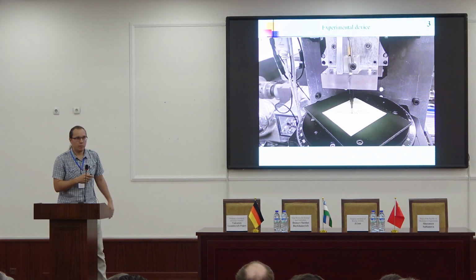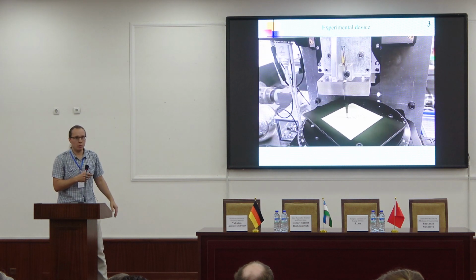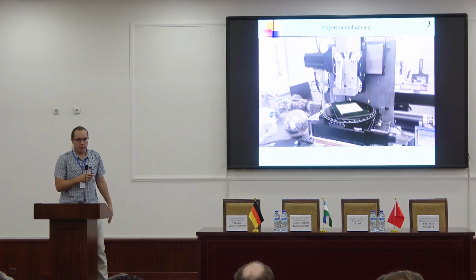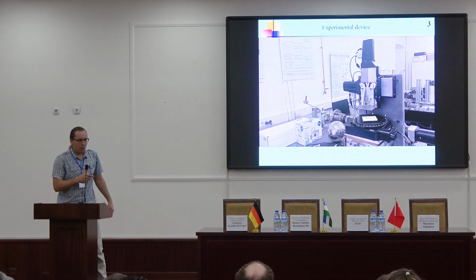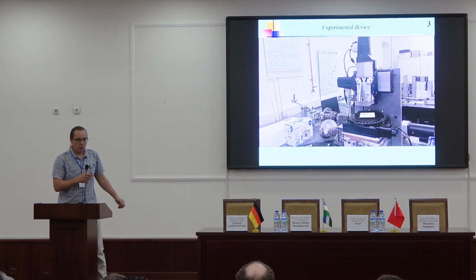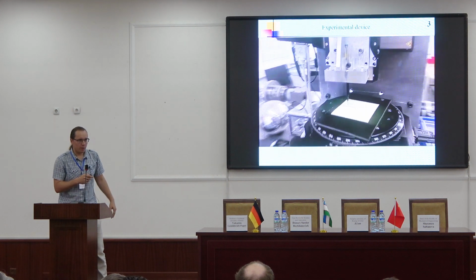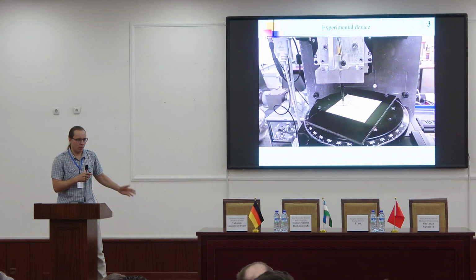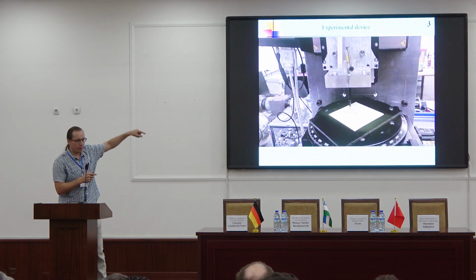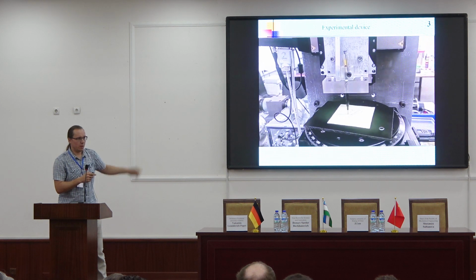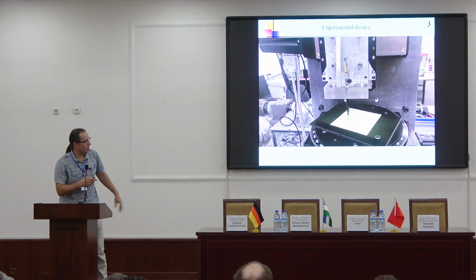It means that with our device, we can use it for investigation of normal contacts, as a linear tribometer, as a rotation tribometer, and we can apply it for investigation of contacts with very different loading scenarios, any loading scenario, and not only for adhesion, just for usual contacts. If we have one body at the upper point and a second body lower, we can move it in different trajectories. It's a universal tribometer in principle.